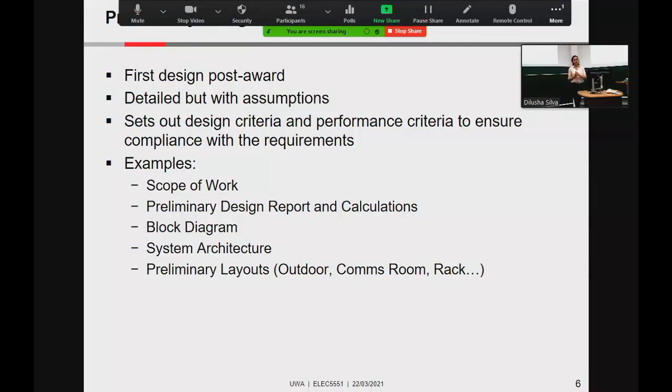For example, one of my projects in New South Wales, I'm designing the fiber optic network for their rail network. The requirements are thousands of requirements. So the bits and pieces here and there where you gather information, for example, they would say all the signaling wayside locations must have at least 4 cores of fiber, but in 2 separate cables.